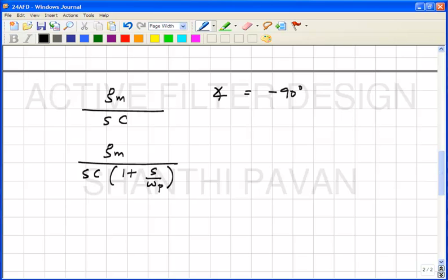And what did we say when we say omega p has to be far away, correct? What is the meaning of far away? No, yesterday we said that respect to the passband edge is only a very crude estimate. We said that our notion of far away must not be related to omega naught or simply Q, but to the omega Q product. Omega p must be much larger than 2Q times omega naught.